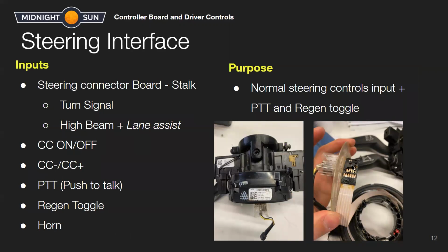The way it works is that there are two endpoints on either side. As the cable turns, this ribbon cable will essentially tighten or loosen, but it has enough length that it wouldn't affect it. And then we're able to route our communications over this ribbon cable around to the other side without having to deal with the problem that the cables will twist as the wheel turns.